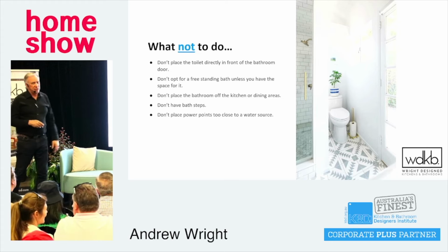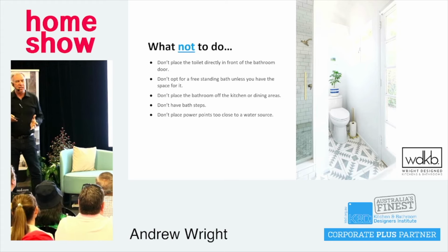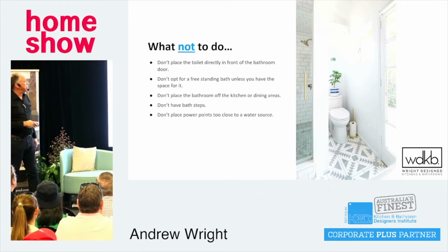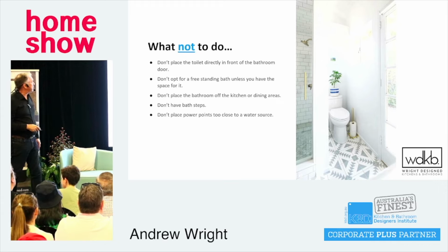What not to do? Don't squeeze in things just because you think they can fit there. You've got to make sure there's enough room. So take this toilet, it's not one of my bathrooms, it's been squeezed into about a 650 space. It's just really not enough space there. This wall should never have been put there. The toilet should have been put somewhere else.